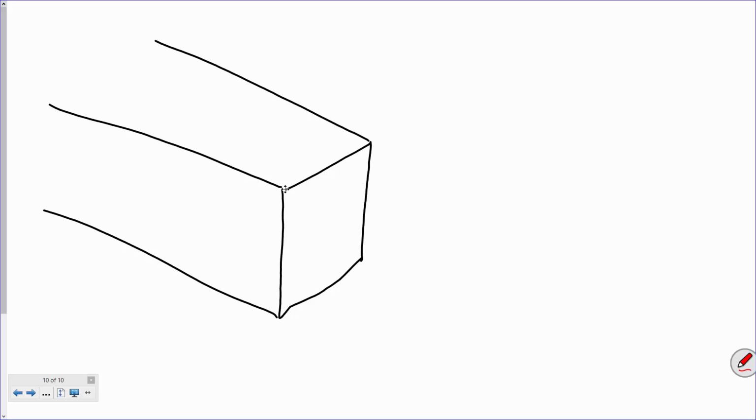And we'll say that neutral axis is something like that. When you have a bending stress profile, that bending stress profile is applied across the entire beam width. So if I have a bending stress profile, it'll look like that across the whole beam width.